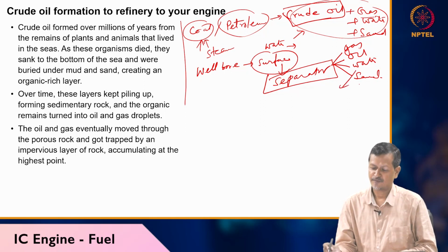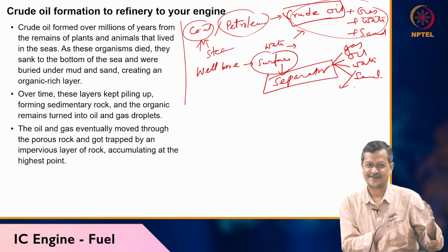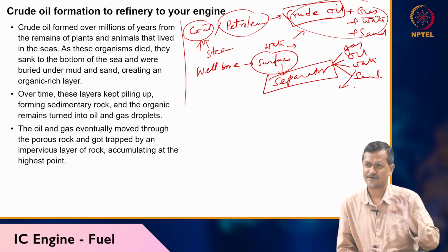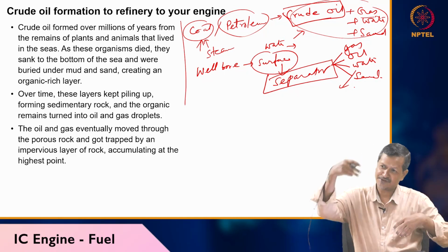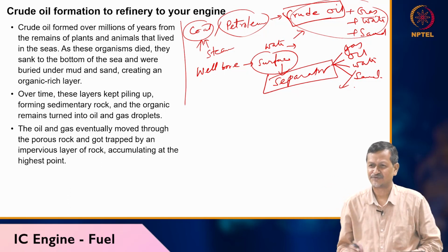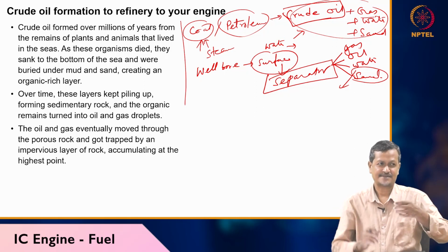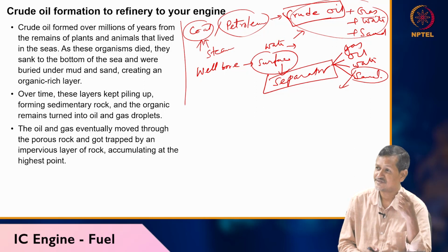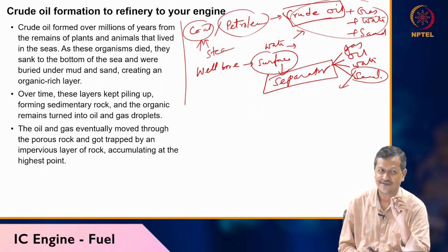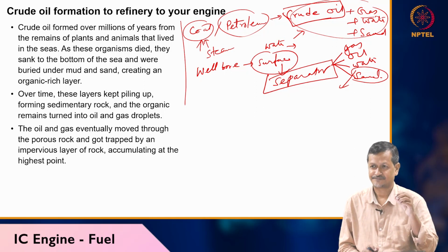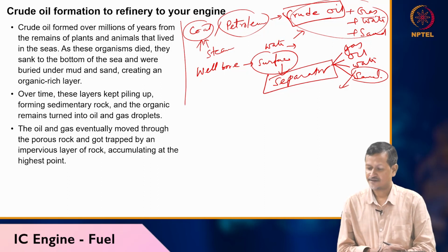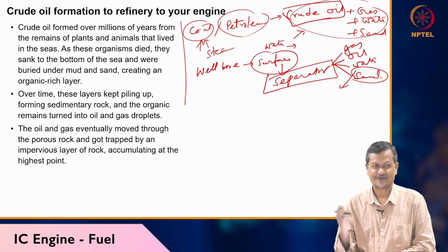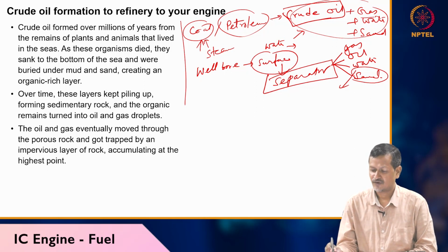Now for water, you have to remove all the hydrocarbons, then you can dispose. Again, disposing randomly is not possible. There are certain government regulations you have to follow. You have to drill another hole and inject there. So there are different mechanisms to dispose water. Sand also will have the same issue. When you are producing oil and gas, sand also will come, and disposing sand is also a challenging job because it will have hydrocarbon. Hydrocarbon coated sand disposing is very difficult, so again you have to separate the hydrocarbons, then dispose.